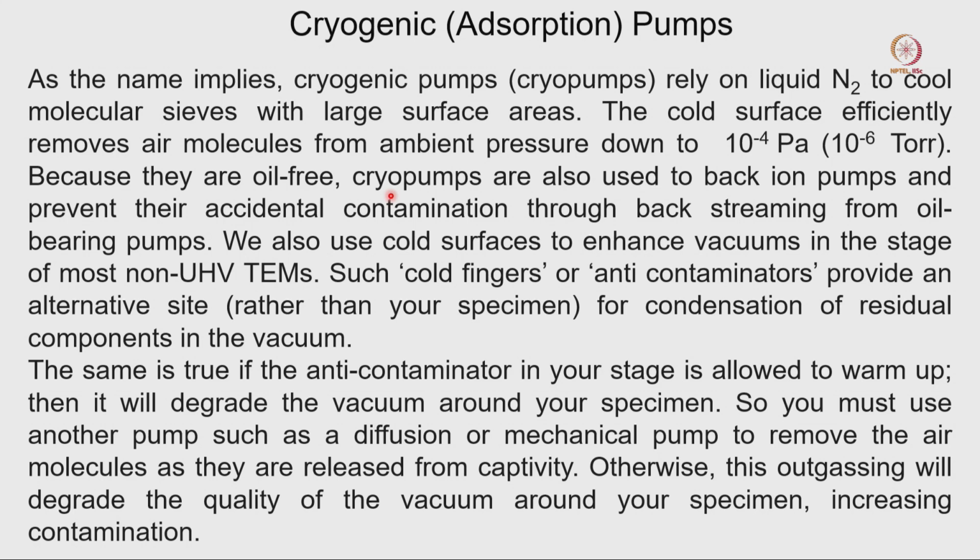Because they are oil free, cryopumps are also used to bake ion pumps and prevent their accidental contamination through back streaming from oil bearing pumps. We are not going into these technical details. Always remember that we are also using some kind of cryogenic pump, where we use liquid nitrogen to trap water molecules and ions to remove those kinds of contamination.